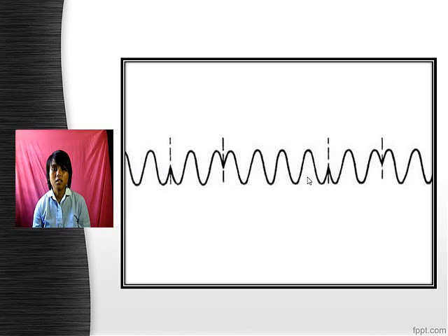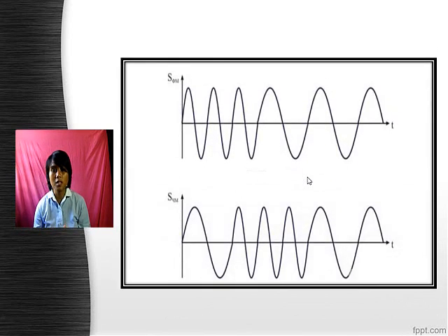In general, phase and frequency modulation are very similar. They differ only in the spectral composition of the modulating signal amplified to the modulator. During pure sound modulation, phase and frequency modulation are indistinguishable. A phase modulated signal at the modulator output has a constant modulation index at any modulation frequency.